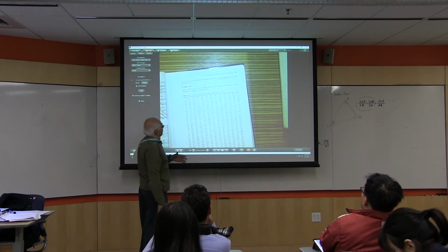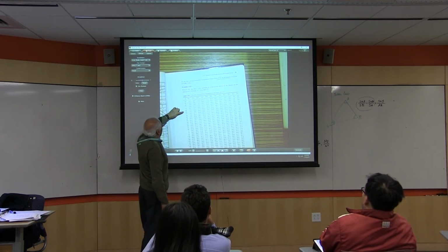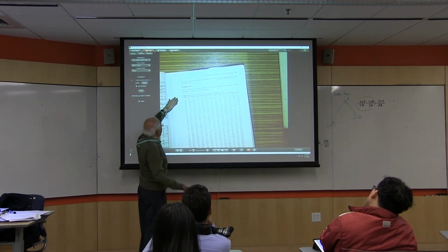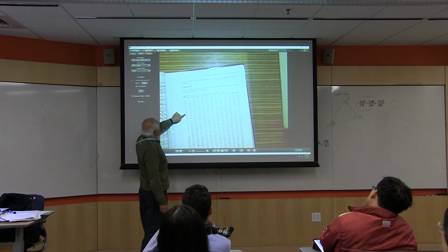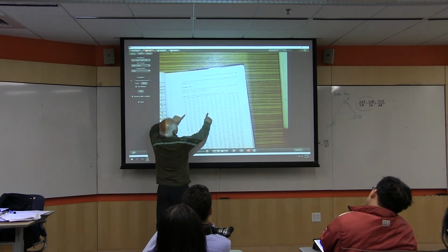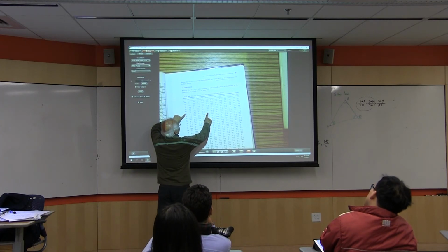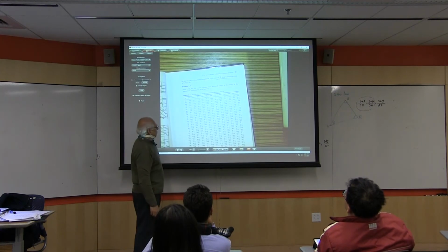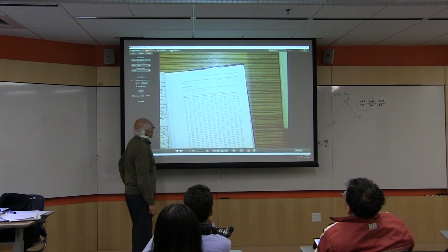So, for example, if you were at, let's say, 55-degree latitude in the month of May, the H naught would be 37.6 megajoules per square meter.